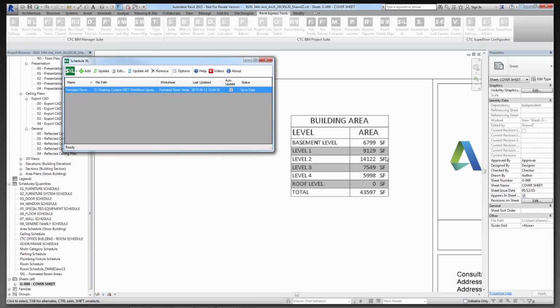So a number of workflows there where I can take data from Revit, kick it out, manipulate that information in a spreadsheet, and show it back in Revit in a somewhat intelligent BIM schedule, right? This data right here came from my Revit model. Now, some of you are probably sitting there thinking, yeah, but you could have done it with a Revit schedule. Okay, I could have done most of this with a Revit schedule. You're right. But this is just an example of something that you could export, reformat, and bring back into Revit.